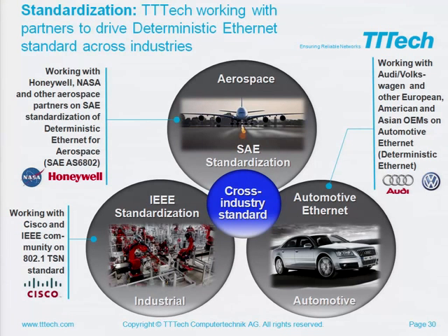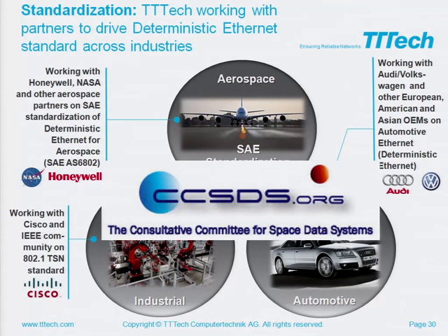Here it is not as highly reliable and available. There is no fault tolerance included here. It goes more to an additional quality of service in terms of latency and determinism. And then there is a big initiative from automotive currently for Ethernet, which is driven by Audi and VW, and there will be another standard for Ethernet within automotive. And currently we are working on a CCSDS standard for time-triggered Ethernet, because the aerospace standard defines the protocol principle, but this would be more in the direction of how to implement the technology itself into the dedicated components.